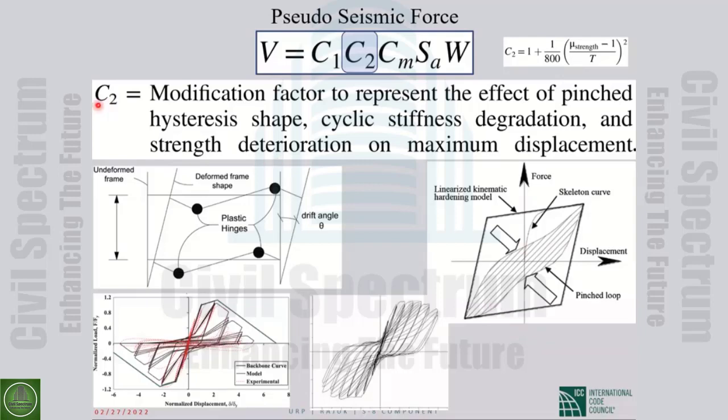So anyhow, all these bad events are due to the detailing. And this is especially true for existing buildings, because for new buildings, if you look at the coefficient formula, in some codes they also put this for new buildings to do performance-based design. There you don't have C2, because for the new building you expect that the detailing will be good.